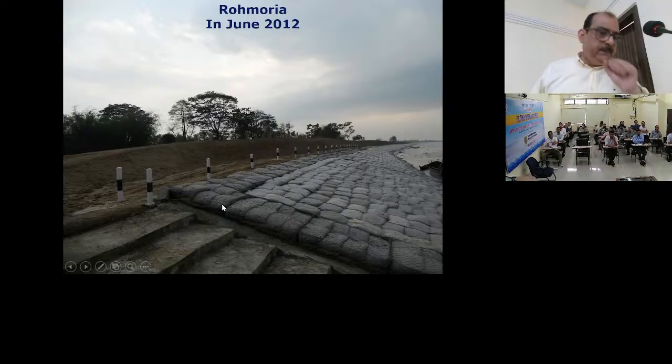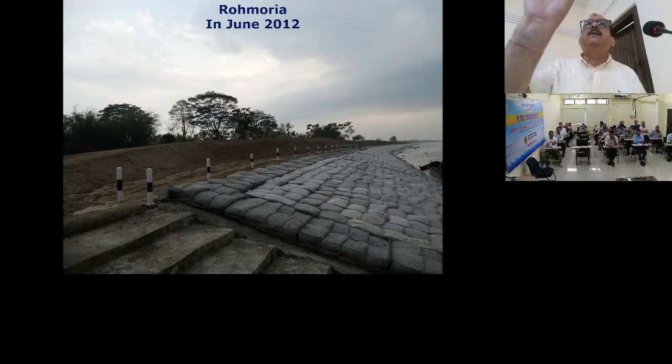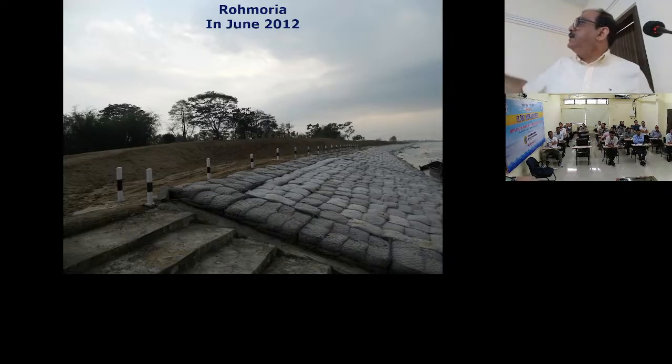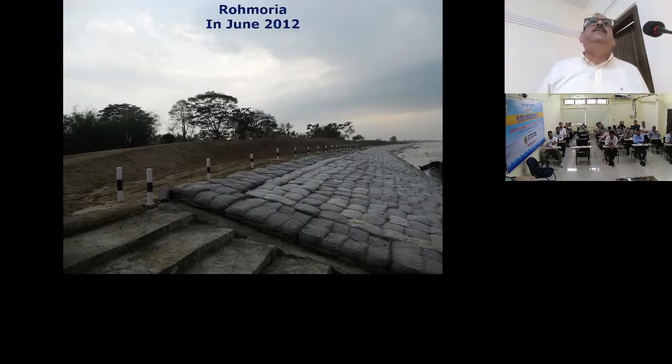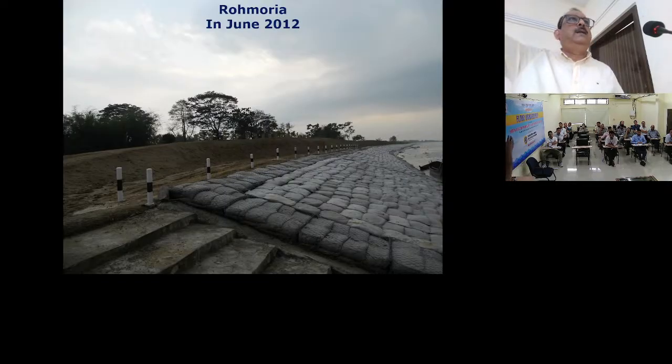Now, there's a problem here. These geobags are vulnerable to ultraviolet ray. Their life deteriorates when exposed to ultraviolet ray. So they work very fine below water level, low water level. But here these were used above low water level because time was not there. Construction of concrete blocks takes a lot of time. But geobags, you only fill up with soil and place it. You see their sides are given. Okay? Now this is still working there, protecting the site. Fortunately, what happens during flood time, all these bags are covered by mud and protected from ultraviolet ray.